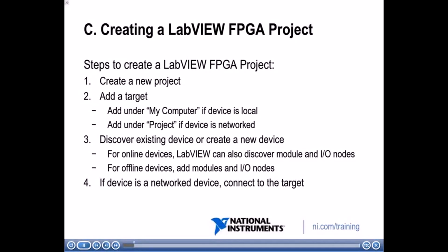In this slide, we see an overview of the steps that are required for creating a LabVIEW FPGA project. So the first thing you want to do is, in LabVIEW, create a new project. Next, you want to add a target.